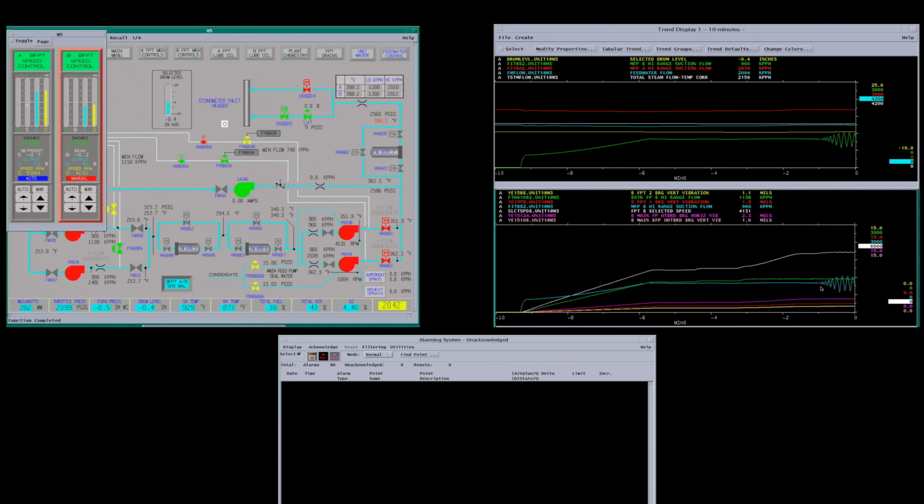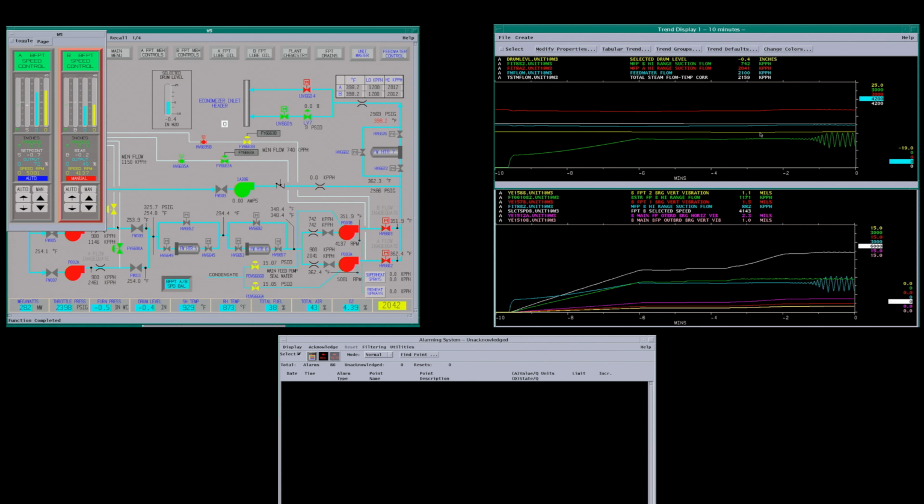So as you can see, we've got a pretty good swing. This graph shows both feed pumps. We got the total feed water flow here. We have the A feed pump, and we got the B pump we just started here. And here's the drum level. So this is swinging pretty good. This is why you drive through this range fairly quickly, to keep the pump from cavitating and swinging.